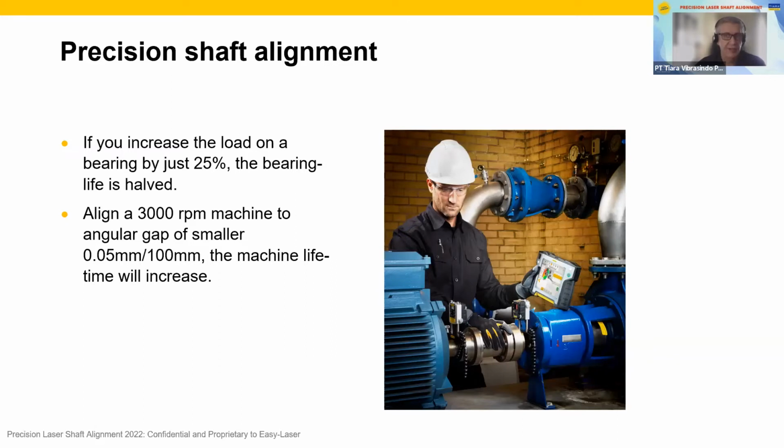But you cannot get even close to that degree with a straight edge alignment, and probably not with a dial gauge indicator either. While it is technically possible to achieve that with a dial indicator, most people, even experienced people, are likely not to achieve this because the dial is not that accurate. There are other related issues. So you consequently need a precision alignment technology, and that's today laser technology.